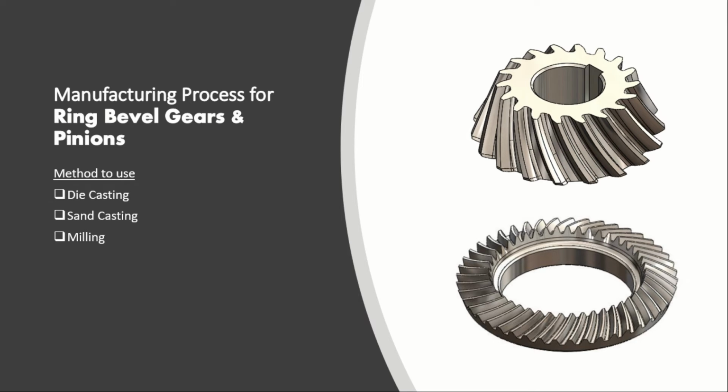First is the ring bevel gear, second is the pinion gear. These gears use the same material and are produced the same way. There are three manufacturing processes. First is die casting, second is sand casting, and third is milling. Die casting and sand casting will go through the finishing process. We also use milling machines to conduct the finishing process.